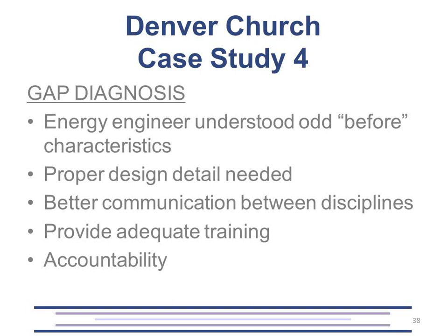And lastly, the sequence of operation and improper set points were discovered by the analyst during verification, so the proper changes were made. Then additional training was provided to the customer and end users to explain the proper operation of condensing boiler systems as well as the other high-efficiency systems installed in this scope.